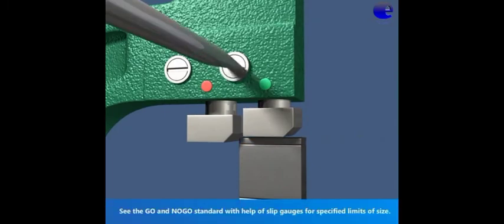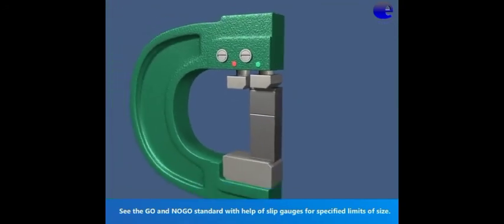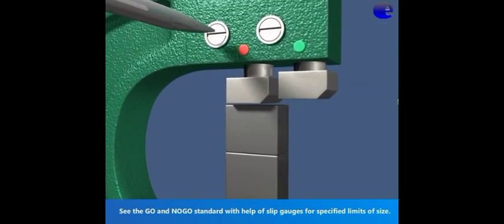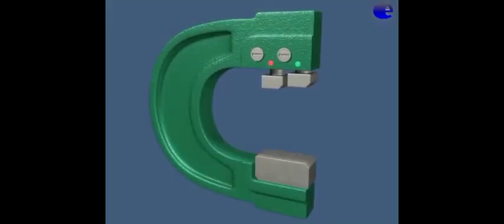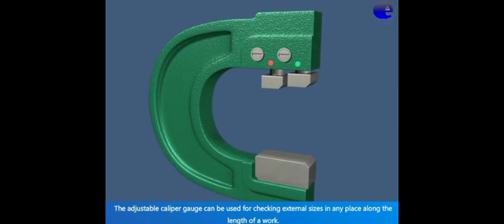Set the go and no-go standards with the help of slip gauges for specified limits of size. The adjustable caliper gauge can be used for checking external sizes in any place along the length of a work.